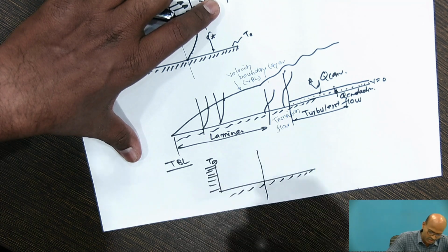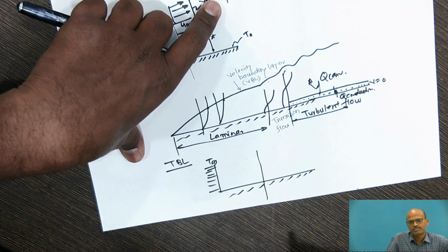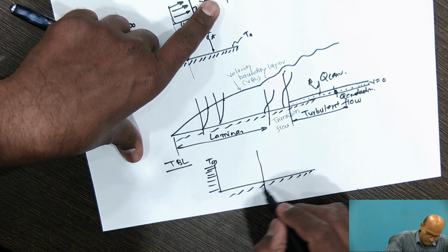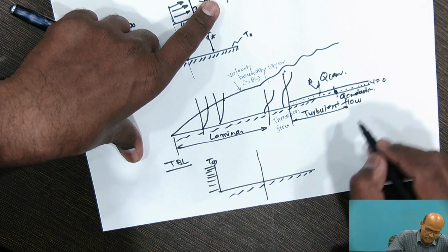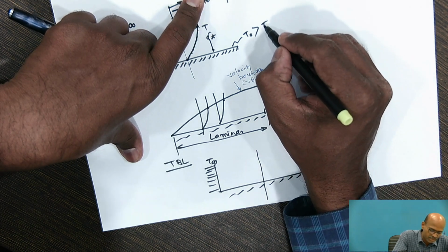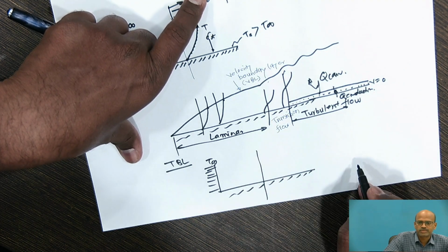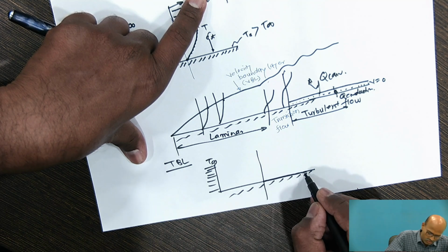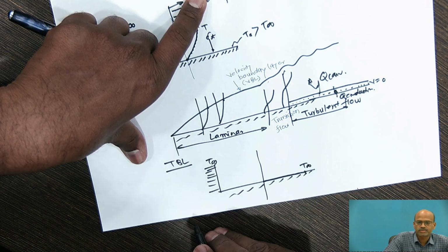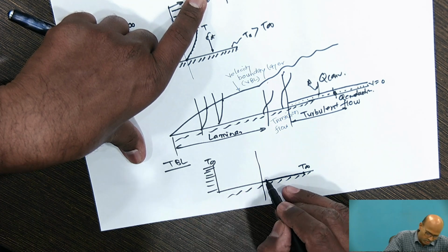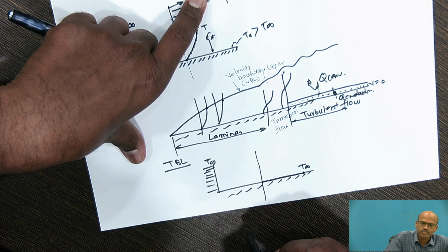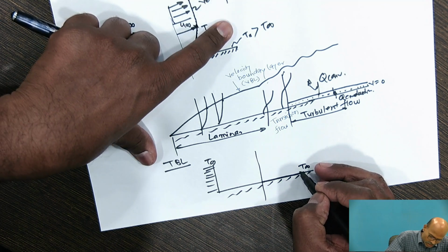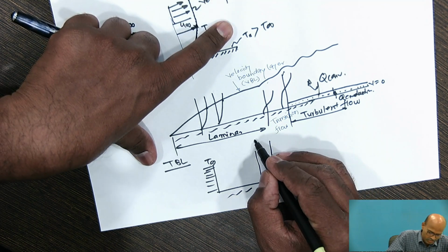At a certain distance, if we start measuring the temperature of these fluid layers, then the layer which is in contact with the surface, where the surface temperature is greater than the free stream temperature, will have the surface temperature, and as we move away from the surface, what will happen? Yes, its temperature will go on decreasing and you will get this temperature profile.